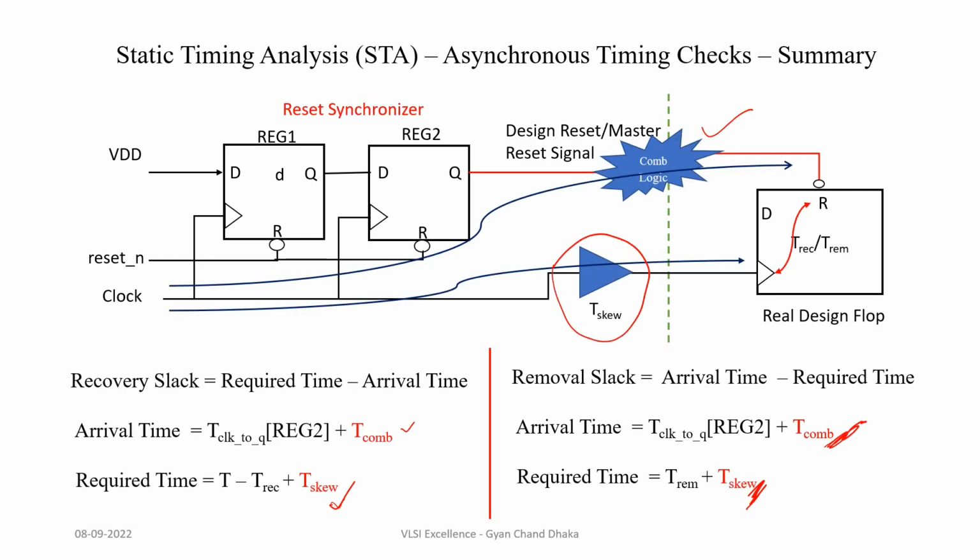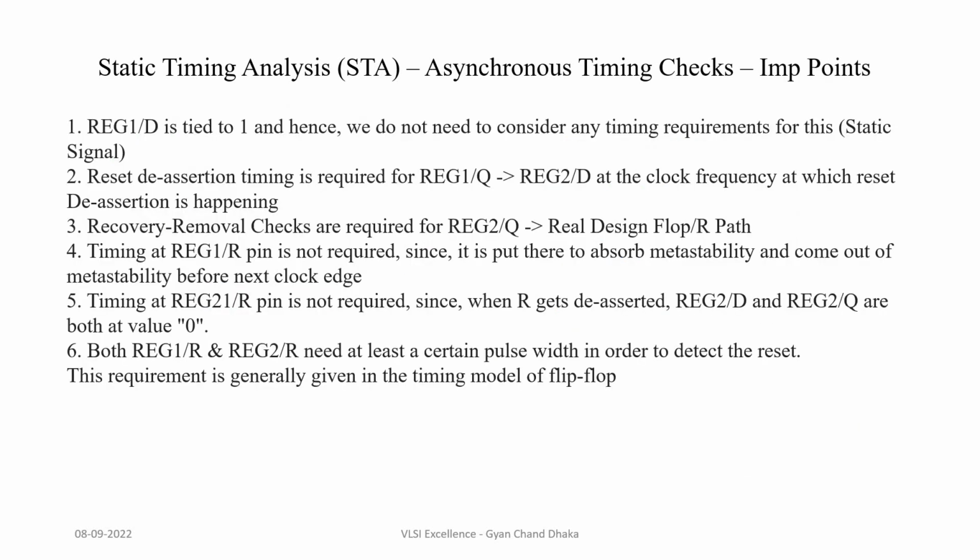So if you see here, our register 1 D pin is basically tied to VDD. So this will basically become a static signal, so we do not have to worry about any timing checks with respect to this pin. So this is one important concept.